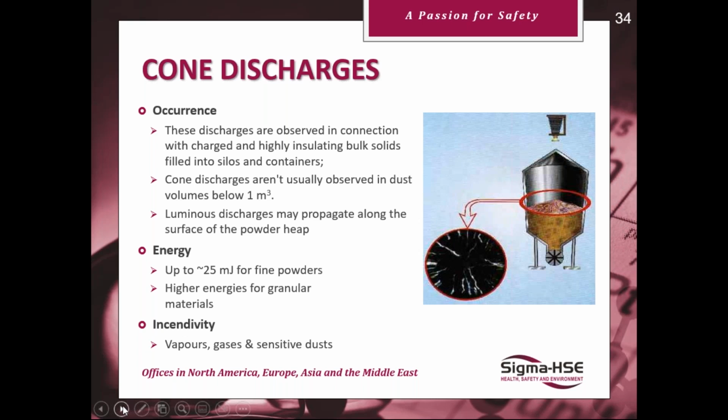The one I got involved with was a silo full of plastic pellets used for secondary windows, for double glazed windows. They had an explosion one night, which blew the explosion vents. On investigation, there was a Japanese engineer on site at the time who said there was a probe in there with a small piece of plastic on it. That plastic would have given a brush discharge to ignite the powder. Well, the powder had an MIE of 10 millijoules, so it wouldn't have been that.